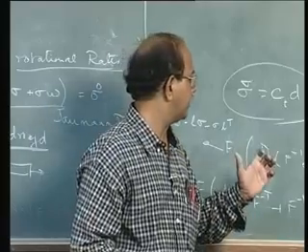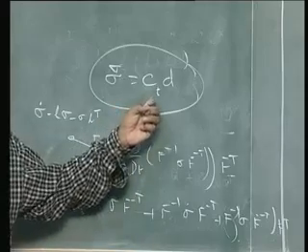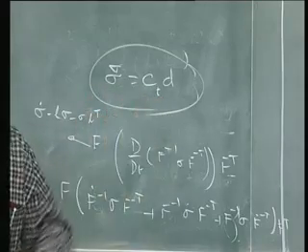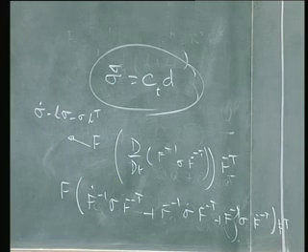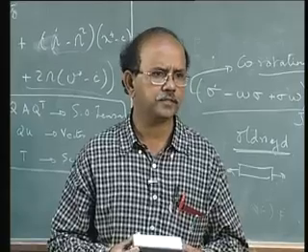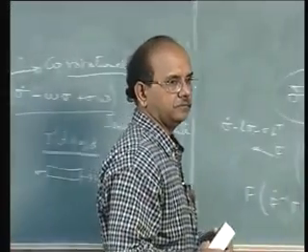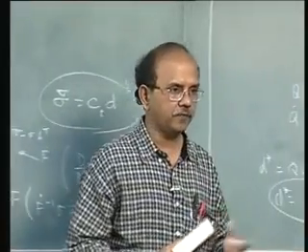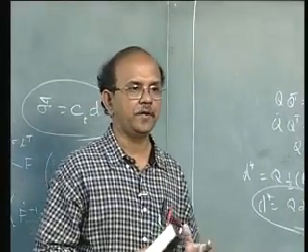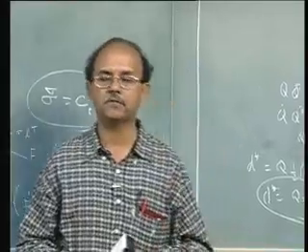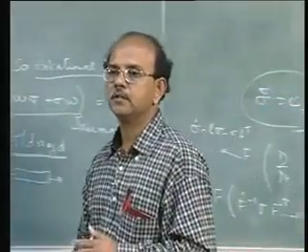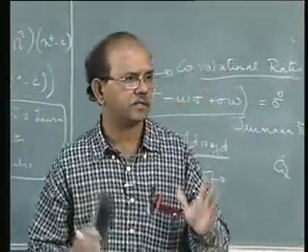Of course, when you use different rates, the C quantity is different. They are not the same. You have to be careful about that as well. These are not the only rates. As I told you, there is what is called the Truesdell rate, which is again very popular. The Truesdell rate operates on the second Piola-Kirchhoff stress. That's also used, but the concepts of all these rates are the same.